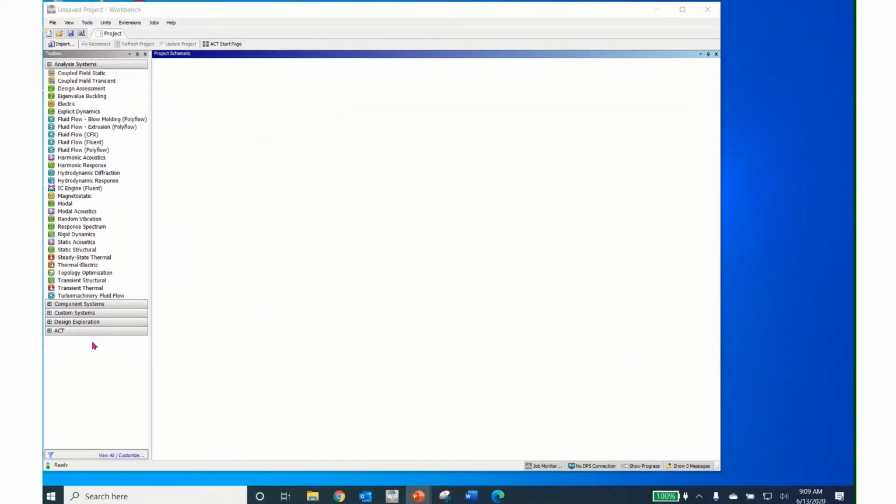After opening Ansys Workbench, left-click on Static Structural, drag it into the project schematic window over the green box. It'll turn red and let go, and we now have our static structural working window. Engineering data has been checked, and we know that the default is structural steel. Although it is highly unlikely that this entire disk is made out of structural steel, the focus of this tutorial is on CAD import, and so we're just going to let the default of structural steel be used throughout the model.